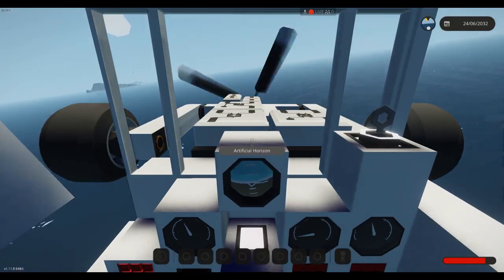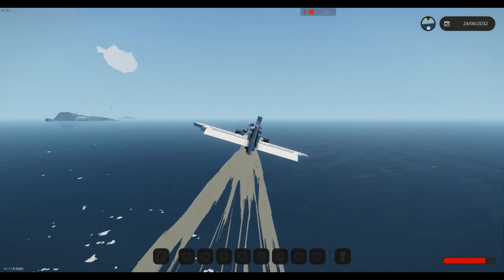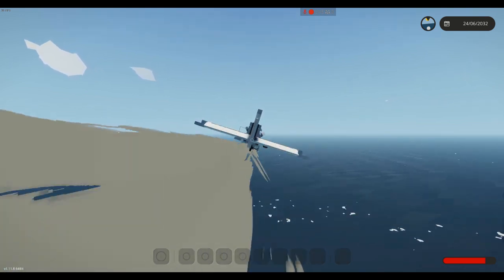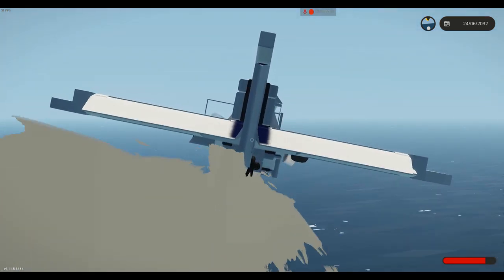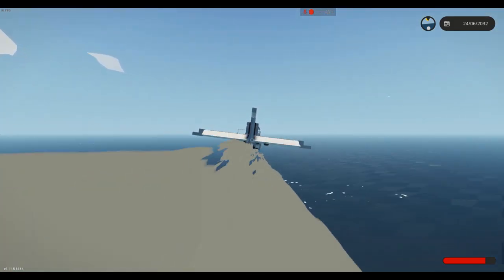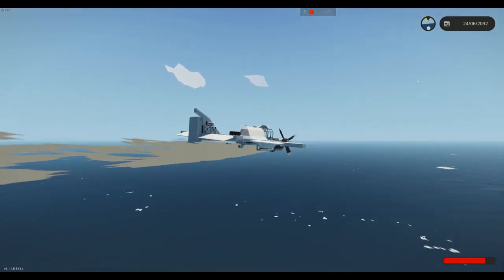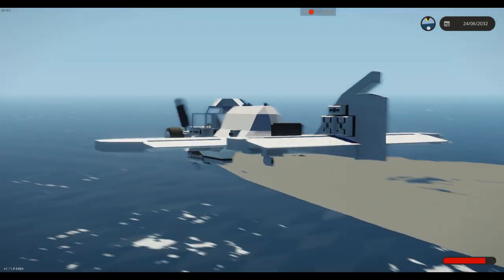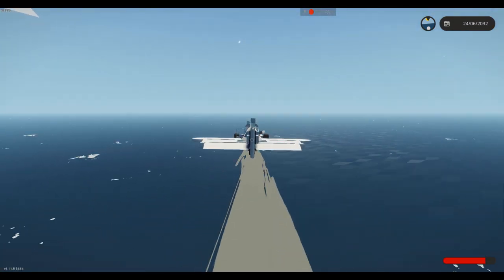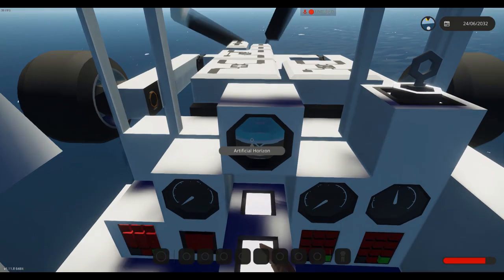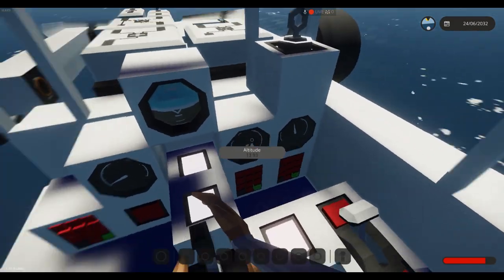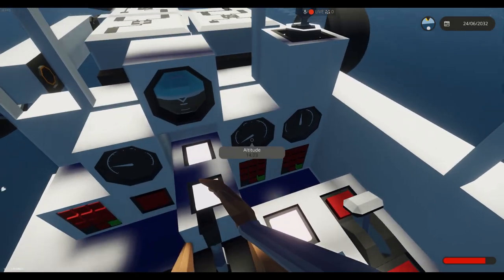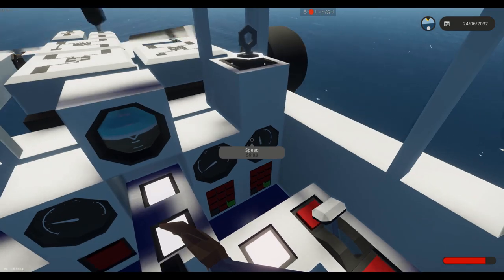And you can see we're going to roll the plane to the right, and I'm just going to let go of the controls. I have let go, and I'm just going to let our bank angle center hold system take over. As you can see, it snaps into place. And it will hold here, nice and center. We can even come down here, look at our gyro, perfectly stable. And look at our altitude, 13.99, 14. It holds it within one value. It holds it close enough.